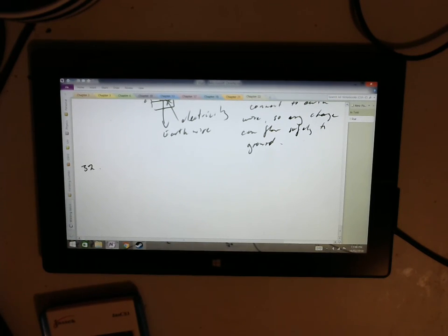Two paralleled 50 ohm resistors are connected in series with three large resistors of 100, 200 and 250. The assembly is connected to a 20 volt battery and an ammeter to measure the total circuit current. A voltmeter and ammeter must be used to measure current flow through and voltage drop across one of the 50 ohm resistors when the main circuit switch is closed.